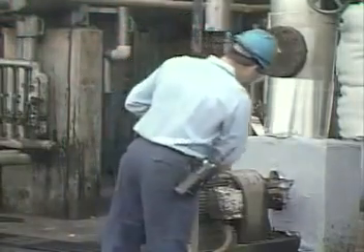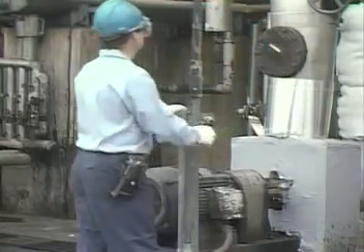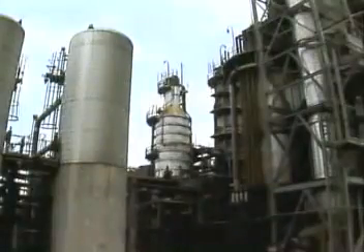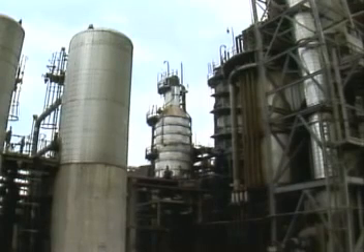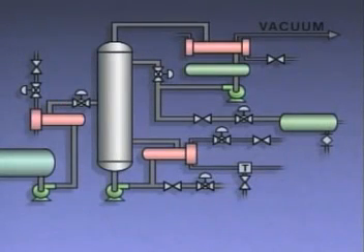After the equipment in a distillation system has been readied for operation, the startup of the system can begin. To demonstrate typical cold startup procedures, we'll use a vacuum distillation system that separates a non-combustible binary feed mixture. Now, if a combustible mixture were being distilled, a precautionary step called purging would have to be performed before allowing the feed mixture to enter the column. Purging involves introducing steam, nitrogen, or carbon dioxide into a column to displace any oxygen that's present and reduce the risk of an explosion.